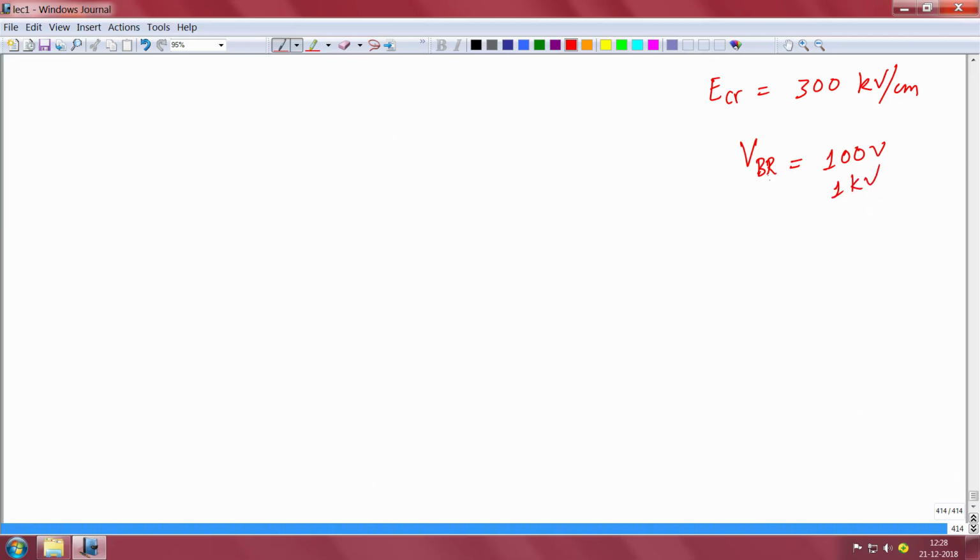So the maximum voltage that you can get, the breakdown voltage, times the maximum speed you can get, that product is constant, okay, which means this is called the Johnson figure of merit, JFOM, and a higher Johnson figure of merit means that the transistor is better as an RF device.